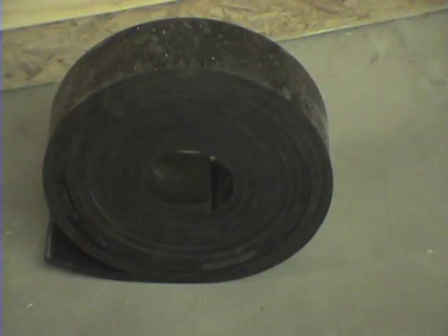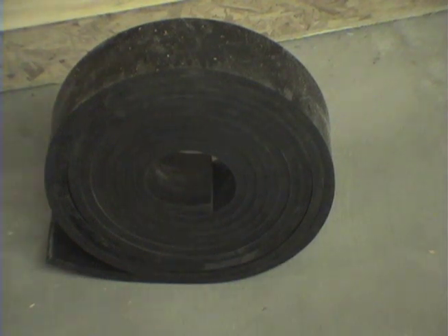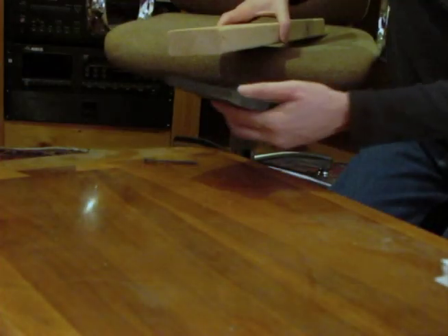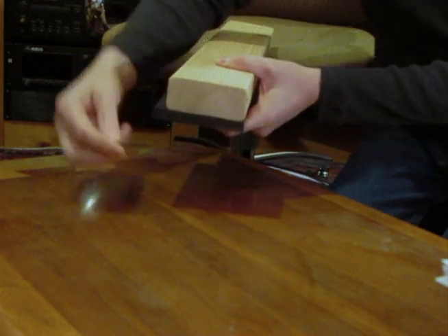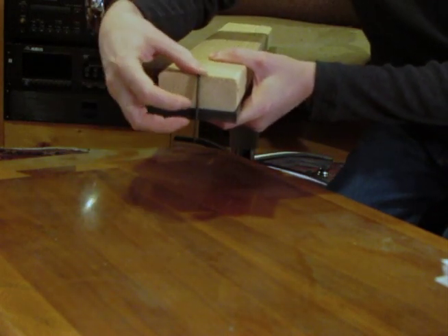As far as attaching the 2x4s to the house beam, we'll use a section of neoprene. Neoprene provides a certain amount of acoustic isolation between two surfaces. Yes, there will be screws that will go through the 2x4, the neoprene, and into the main beam. And this will be an acoustic short circuit and should be avoided if maximum acoustic isolation is needed. The neoprene in this install is used to contribute to the decoupling effect. The bulk of my decoupling will come from the resilient channel used to hang the drywall later.